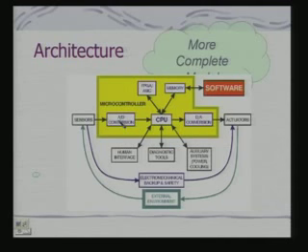These AD conversion blocks actually provide the interface to the sensor, and DA conversion blocks actually provide the interface to the actuators. Because an embedded system which is situated in an environment is expected to receive sensory inputs and actuate the actuators to change the external environment. So, these two are very essential and integral components in the majority of embedded systems.